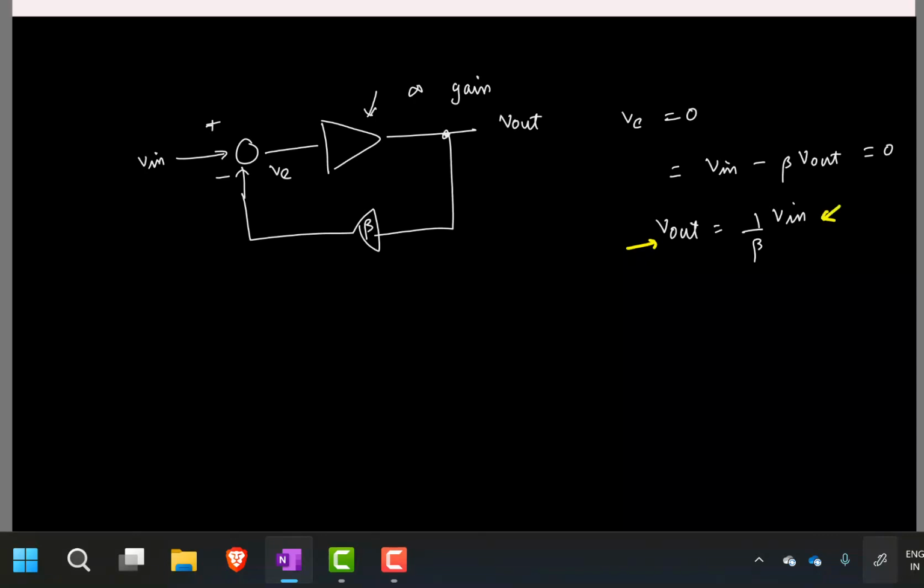This is mathematically. Now as a circuit designer, it makes more sense because, let us say take the amplifier in open loop and apply the input V in. The actual signal that goes into the amplifier is V in itself, right? But here, let us say this has not infinite gain also. What is the actual signal that goes to the amplifier? The error signal. And logically, do you think the error signal will be smaller than V in or larger than V in? It will be really small. As long as you have decent gain, the error signal is going to be small. So in closed loop, the actual signal that goes into the amplifier is really small.